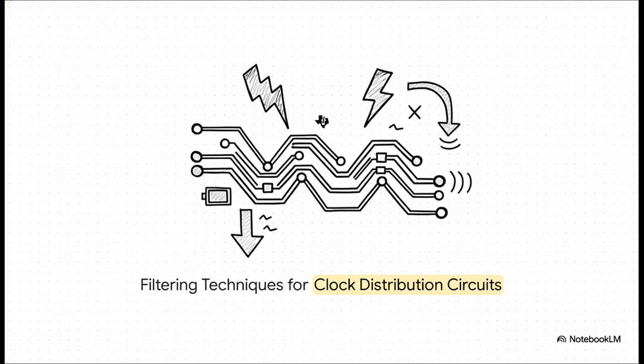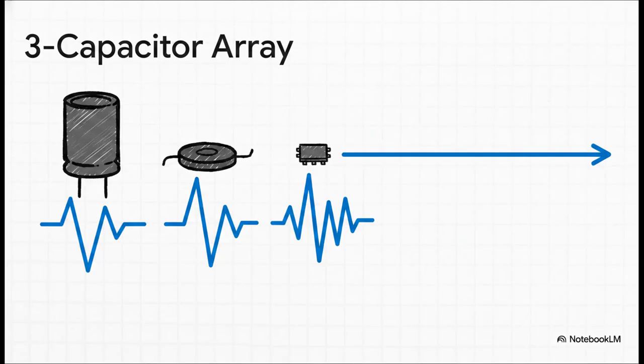We're looking at some engineering application data from Texas Instruments here, showing exactly how bypass and filter capacitors are used to crush AC ripple and stop dangerous voltage droop in our DC circuits. And notice, a single bypass capacitor just isn't going to cut it in modern high-speed designs. You need a multi-value capacitor array.